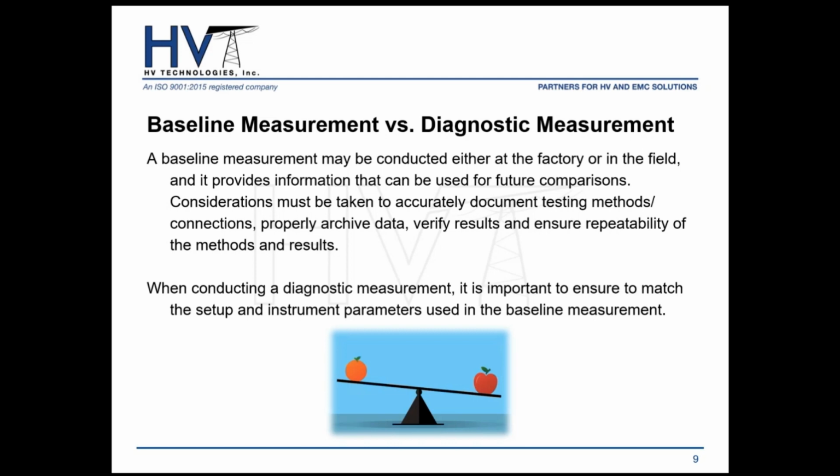Since we're talking about a very unique fingerprint or signature for that transformer, a baseline measurement may be conducted either at the factory or once it's in the field, and it provides information that can be used for future comparisons. Certain considerations must be taken to accurately document the testing methods and connections. Make sure you properly archive the data, verify results, and ensure the repeatability of the methods and results.